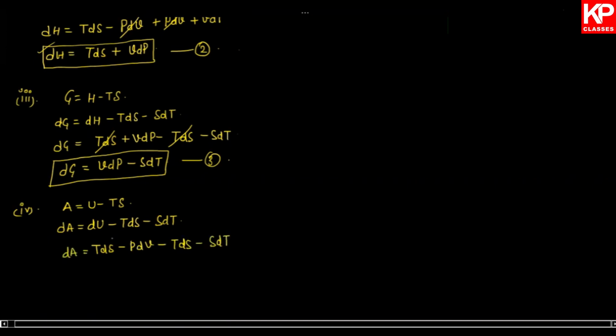So you can again cancel this TdS term, and you will get the expression dA equals minus PdV minus SdT. Okay, and this is expression number 4, right?